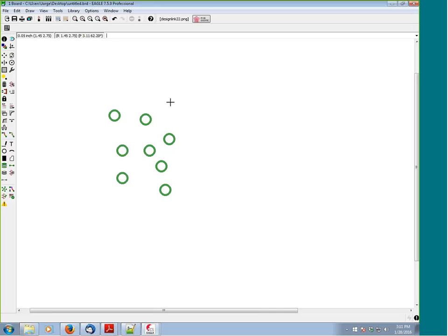Let's say in a board I have an RF chip and also a DC-DC converter. Usually what I have seen people do, let's say with a 4-layer board, is make 2 layers of ground. For example, the top level is a signal level, the bottom level is also a signal level, and the middle 2 layers are the ground level. Are we supposed to keep those grounds separated and connect them together at one point where it connects to the outside ground, or is it better to put as many vias as we can to make a solid ground between the 2 layers of ground?